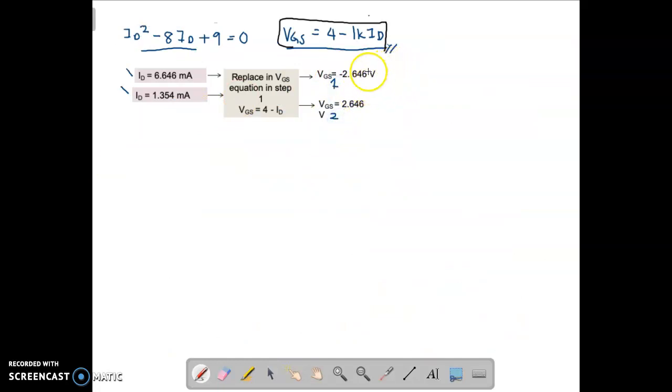So now we need to know which VGS and which ID is reliable in this that we are going to choose. Are we going to choose VGS1 or VGS2? We know that in order for the current to flow, your VGS must be more than 0. If VGS is less than 0, it will be cut off. So VGS1 is less than 0, VGS2 is more than 0. So now your VGS1 is actually, your transistor is off, so you cannot use your ID1. So the final answer is you need to choose VGS2.